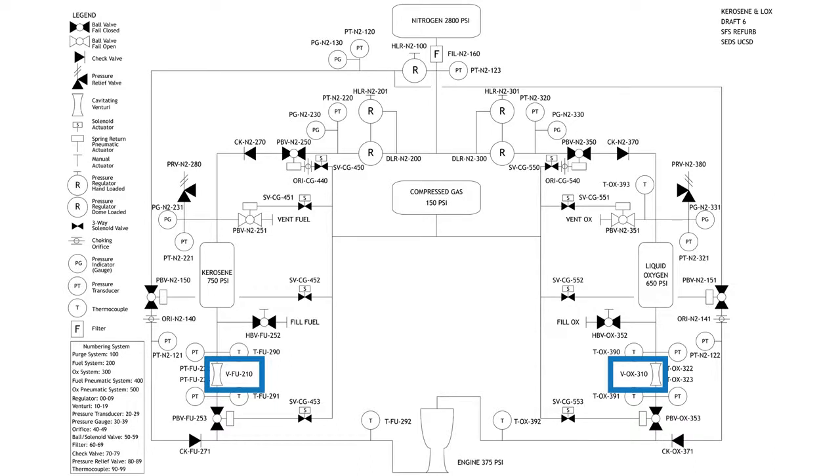And knowing these flow rates is very critical for when you're testing your engines, because you need to know your exact inlet mass flow rates, and you need to know exactly what's going into your system and how fast it's going. The reason you need to know these values is that it gives you your engine efficiency and your engine chamber pressure. But basically that's why you need the cavitating Venturi. So the way we're designing the system is that we have this Venturi take up a bunch of flow, and we're purposely choking it through that Venturi, and when it comes out through the outlet, we know exactly what's coming out, so we can control the flow that way.